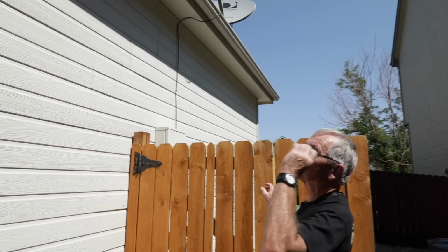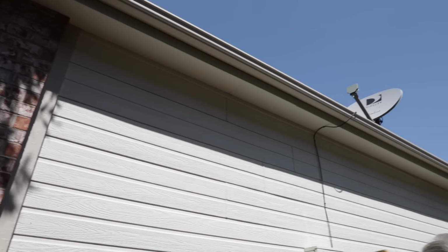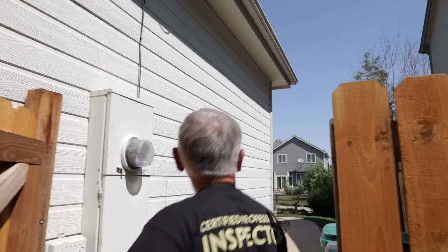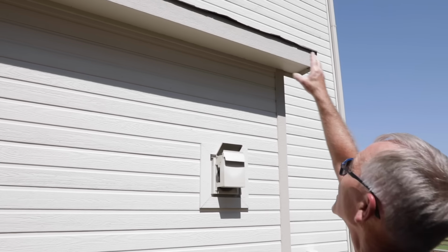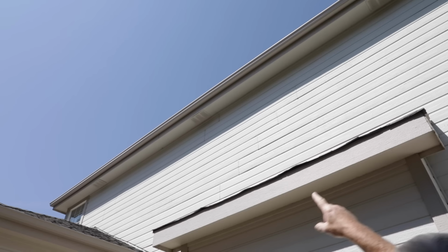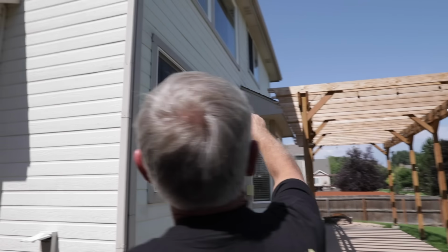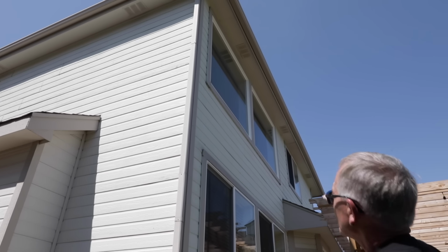Okay, we're back over here on the east side of the house, so we're going to start looking really closely in the corner on our soffit and our fascia. Everything down here on the first floor looks pretty good. Now I'm going to be looking up towards the second floor. I can see that we've got our soffit vents for the attic space in there. Move around here to the back. You can see the vents as well. This is a good time to observe these soffit vents. That's all going to be part of your attic inspection later, but this is the best time to view those.